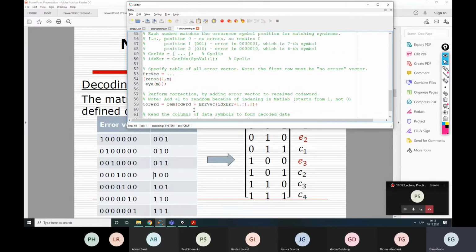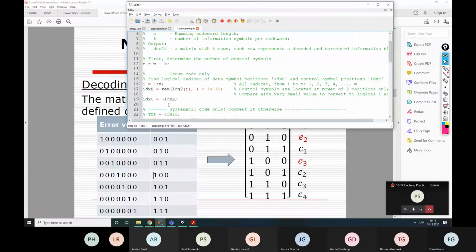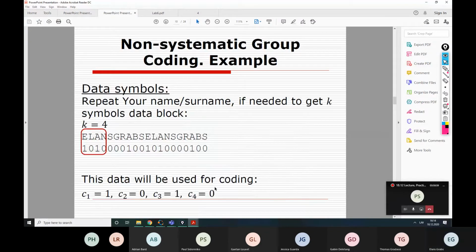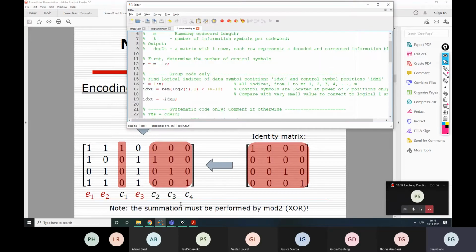Basically, in this line, we select only symbols in non-systematic positions. We only select these symbols because the code word includes also error correction bits, which we no longer need. So we need to remove them from our code word and read accordingly the 3rd, 5th, 6th, 7th, 9th, 10th, and so on symbols. And these indexes have been calculated for you here.